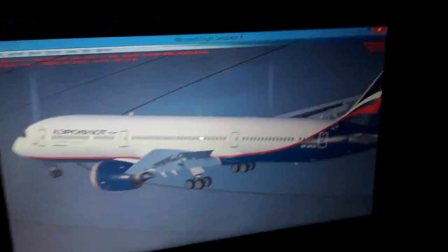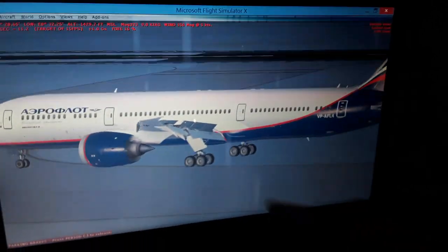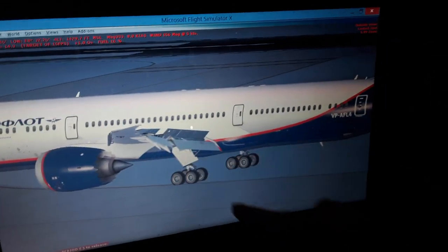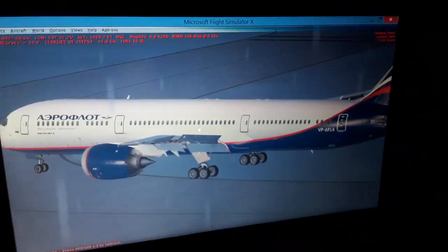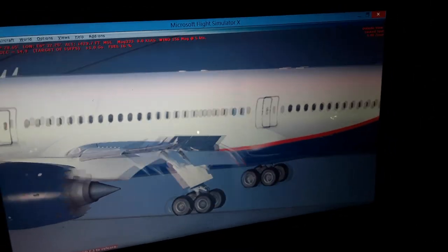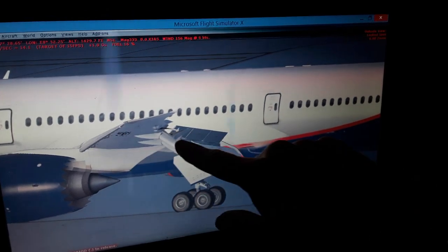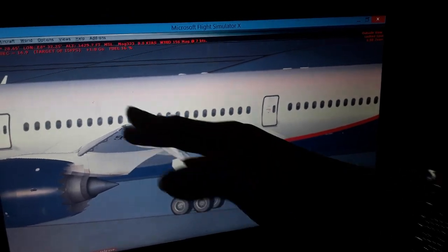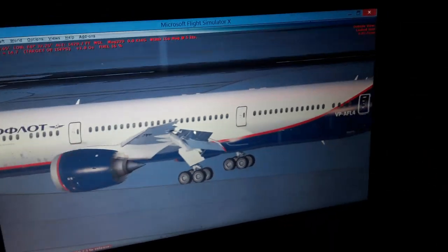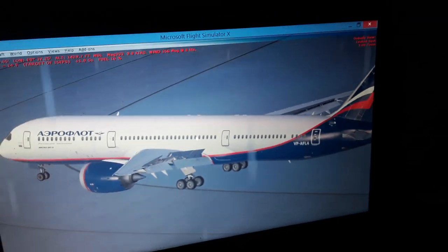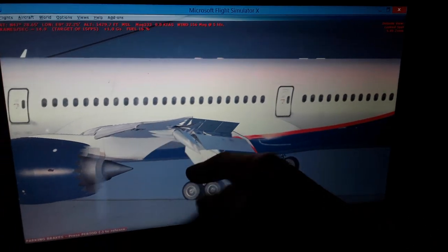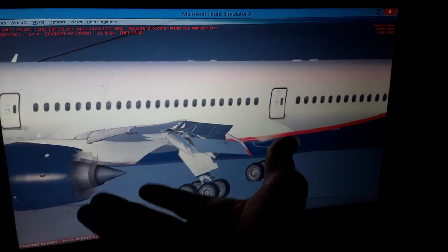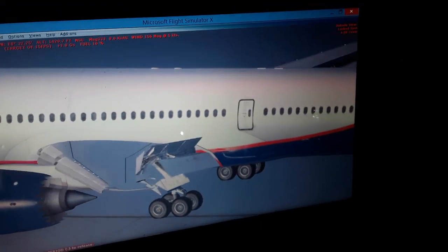Also, the bottom surface of the wings is more flat. When we accelerate for takeoff, like 140 knots, we have the flaps extended like this, and the bottom is more flat than the top. With the flaps extended, we have an angle of attack like this, so the airflow, using the Bernoulli theory of fluids, is moving much lower below the wings, so we have higher pressure below the wings, which pushes the wings up into the air with the weight of the aircraft.